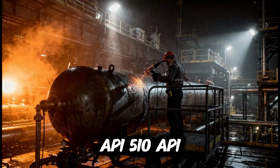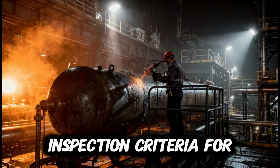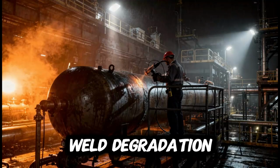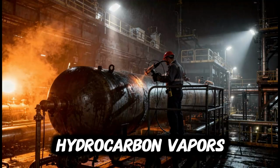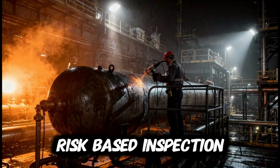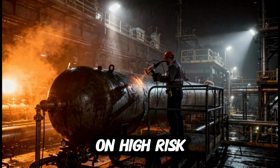API 510, API 570, and API 653 provide sector-specific visual inspection criteria for pressure vessels, piping, and tanks respectively, defining acceptance limits for corrosion thinning, crack indications, and weld degradation. Environmental factors such as humidity, salt spray, and hydrocarbon vapors require inspectors to select corrosion-resistant equipment and implement strict contamination control procedures. Risk-based inspection frameworks prioritize visual examination frequency based on consequence of failure, ensuring resources focus on high-risk assets